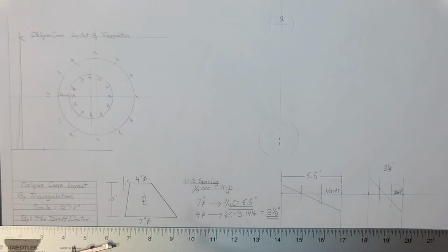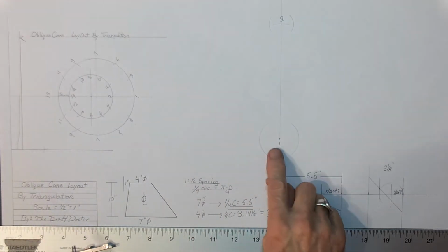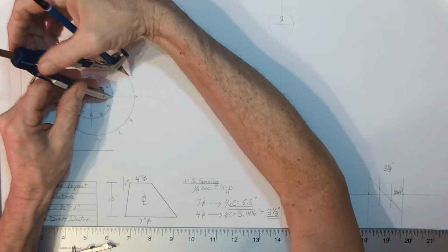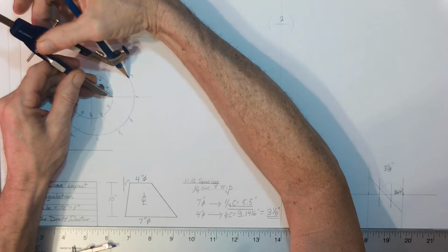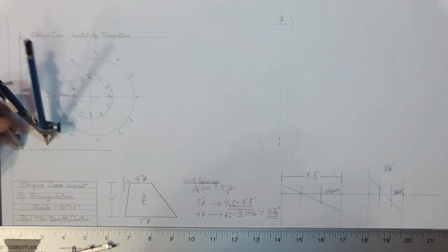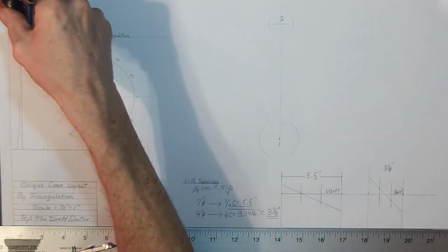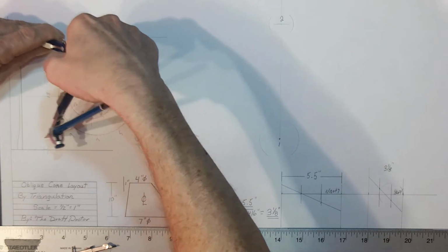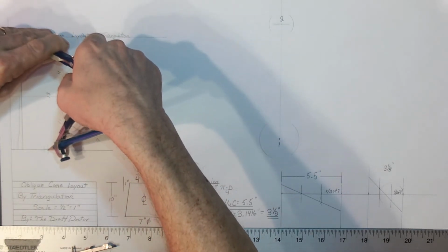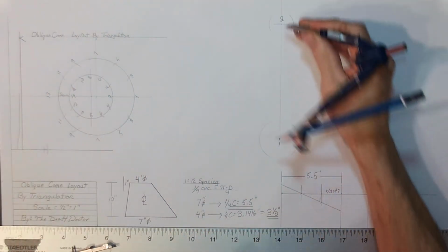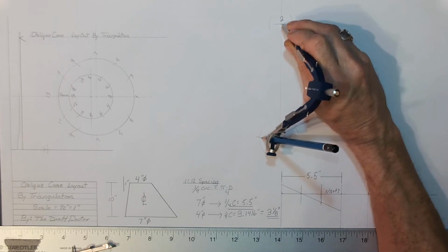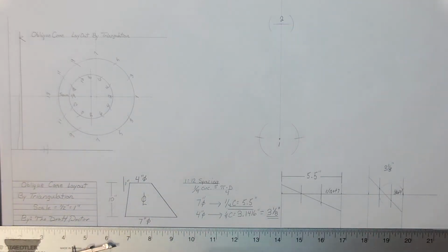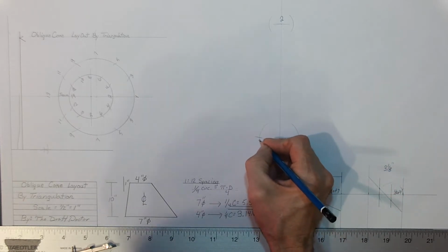I'm going to go back to my working drawing and do a little triangulating now. I've found 1 and 2. From 1, I've located 3. It's on that arc. Now from 2 to 3, if I take my plan view of 2 to 3 and plot it on my true length triangle, there's 2 to 3. Here now is the true length of 2 to 3. And from 2, I can find point 3. Here is my point 3.